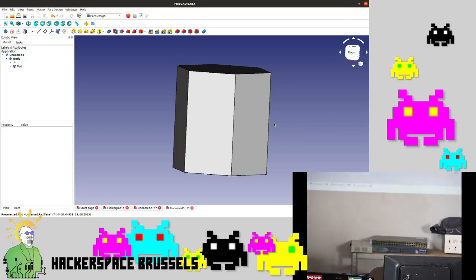Yeah, so that's where the creation of the body comes in. So you're in Part Design, so you select the sketch, and then you click on the little blue one there. Yeah, and then you click XY plane. Now you should be ready.